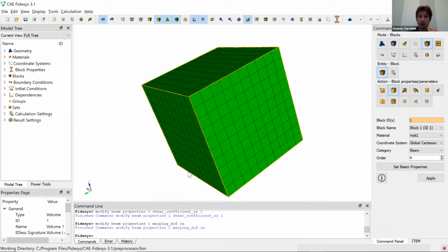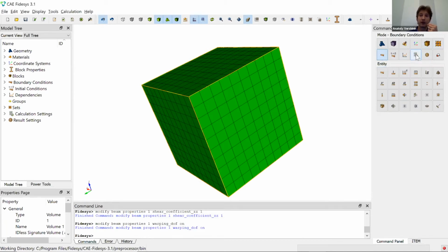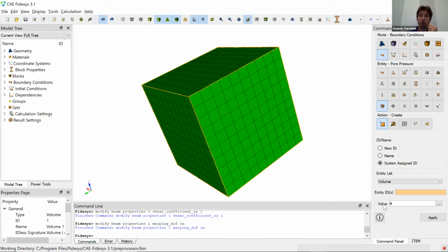And the last but not least step of the workflow to specify the simulation model is to choose a boundary condition and analysis type. So for the boundary conditions, as you could see, we extended the list of possible conditions, forces, pressures, additionally to what is available in the classical basic version of Cubit. For example, if we speak about geomechanical models, one could specify the pore pressure parameter, or one could assign the fluid flux.